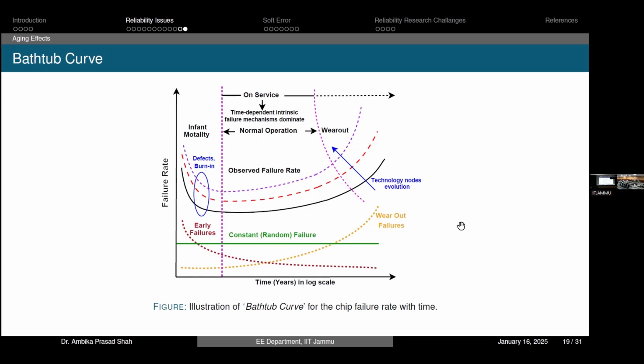So basically, in the last lecture, we were discussing the reliability concern. We started discussing reliability, where we talked about time zero variabilities and time dependent variabilities, which we called the temporal degradations. And we understood how NBTI, PBTI, HCI, TDDB, and process variation work. What is their impact, and with scaled technology or lower technology nodes, how are they going to impact the performance of your circuits and systems.